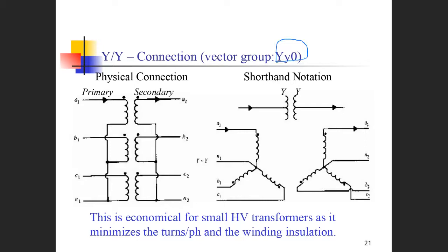Here we are just looking at one simple case. The dot here: if you look at the nameplate of a transformer, you will find a simple drawing showing the connections of the transformer, and for each connector it shows which connector corresponds to which. The dot means the polarity.